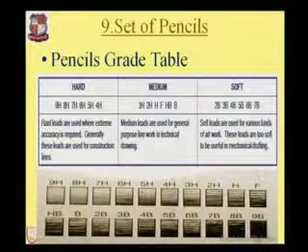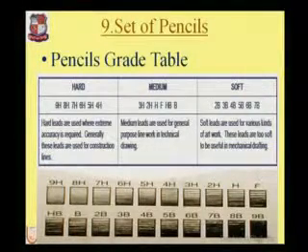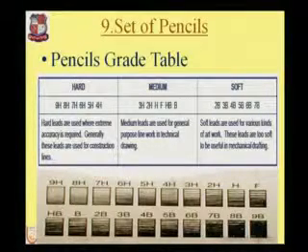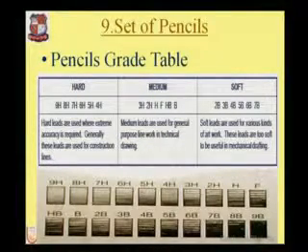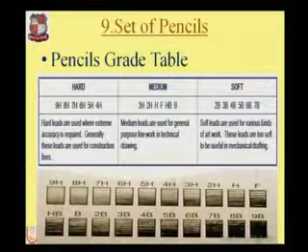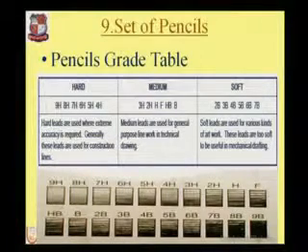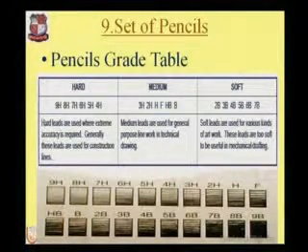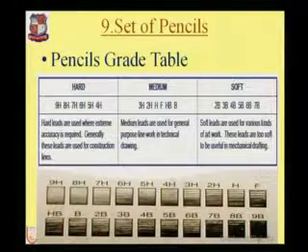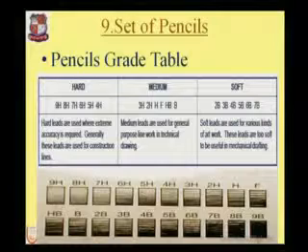For hard grade pencils, as we see in the table below, the different shades of the grades are given. The 9H consists of a very light shade, means by using the 9H pencil light drawings are possible. Same for 8H, 7H, 6H, 5H and 4H. They are comparatively light, and depending upon the application we can draw the different construction lines.